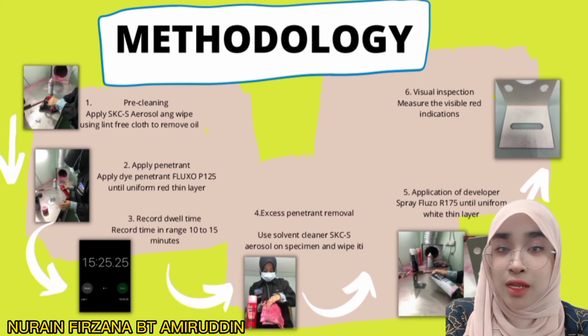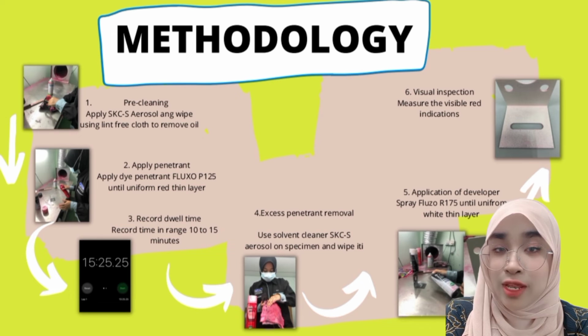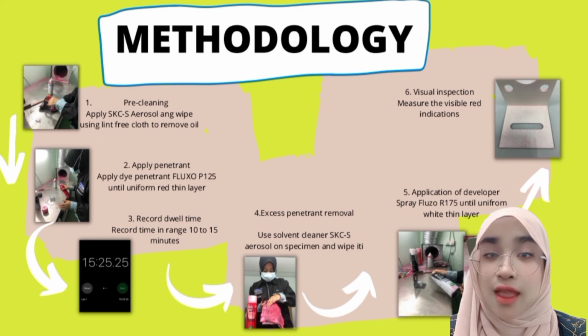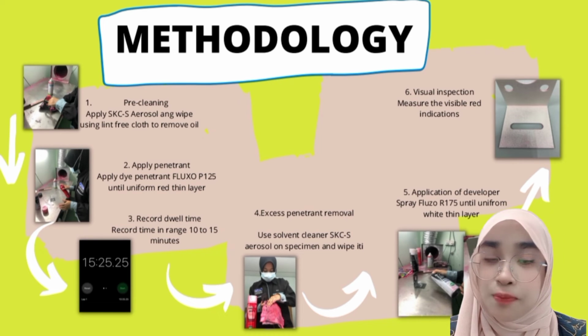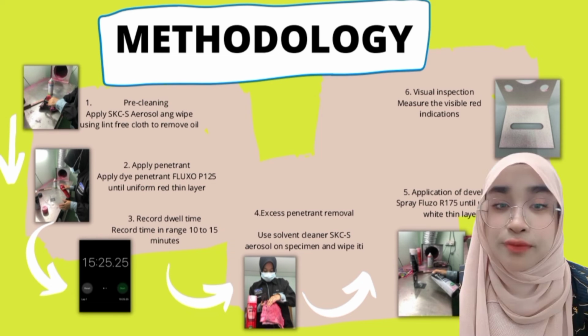Hi, I am Nurain. Today I will explain the process of how to conduct the liquid penetrant testing. Step 1, surface preparation. Pre-clean the specimen by applying solvent cleaner and wiping with a lint-free cloth to remove oil.